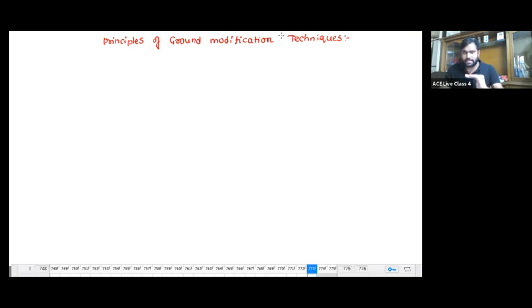When does the liquefaction or quicksand condition occur? Though the soil is fine sand and silt, if there is an earthquake, then liquefaction comes into existence. And if there is an upward seepage such that the upward seepage pressure equals the submerged pressure, gamma w into h equals gamma dash into h, then the soil will fail. So what I can infer is, no soil is a failed soil or a vulnerable soil. The soil becomes vulnerable or fails based upon the design considerations. If you do not design properly, or if you design poorly, then obviously the soil will fail.